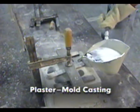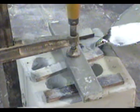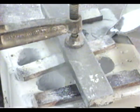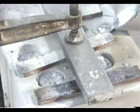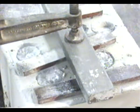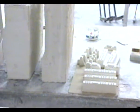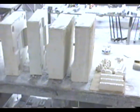Casting in plaster molds is a precision process for aluminum alloy, low-lead copper, and zinc alloy parts. Ferrous metals are unsuitable for plaster mold casting because the molds cannot withstand their high melting temperature. Plaster molds and cores are made largely of calcium sulfate or gypsum and water.